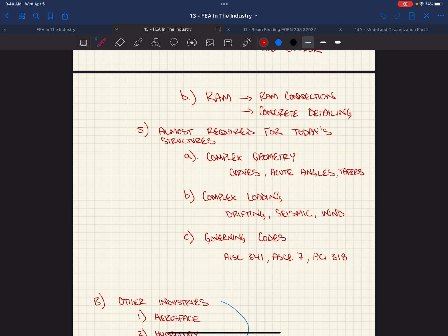So you come up with your earthquake loads, but then when you're doing some of those special detailing, you have to do your capacity limited design. Yep. And which is usually much higher loads than the earthquake. So like what you just said, how does that happen in the real world? That's what I was kind of wondering when I was working through it. I was like, okay. Well, so even with my seismic load case, it's like nothing compared to my capacity limited design.